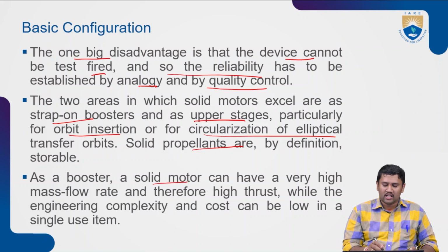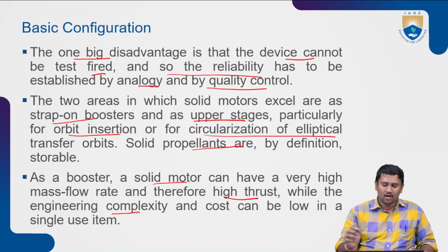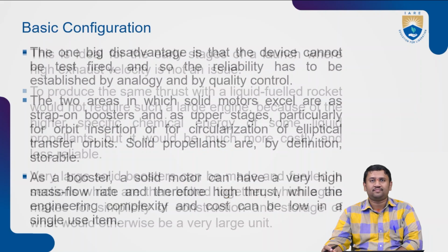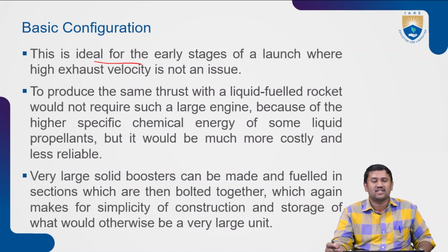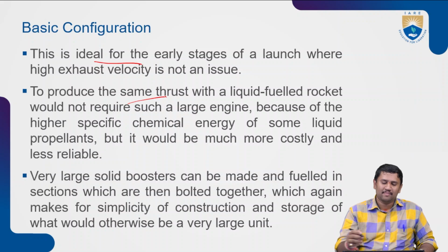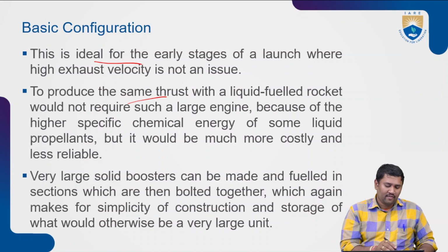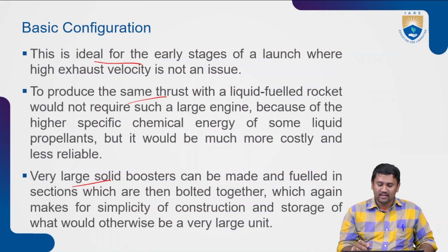Now, as a booster, a solid motor can have a very high mass flow rate as well as high thrust, while the engineering complexity and the cost can be low in a single use item. This is ideal for early stages of launch where the high exhaust velocity is not an issue. To produce the same thrust with a liquid fuel rocket engine would not require a much larger engine because of the higher specific chemical energy of some liquid propellants, but it would be more costly as well as a less reliable method. Very large solid boosters can be made and fueled in sections which are bolted together,